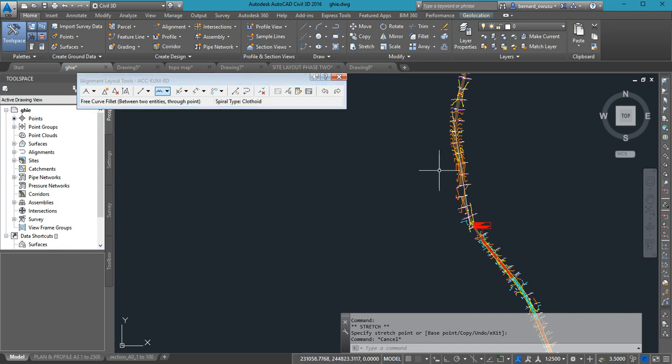Sometimes you may have a number of alignments. It's the same layout tool, but you have to be sure and check and see what name is there, the alignment name. If not, you may be using a different alignment to edit another alignment, then it will not work. So make sure that it is the alignment you are working on that you have here. Whatever is down here is the same for all. So you select this one.